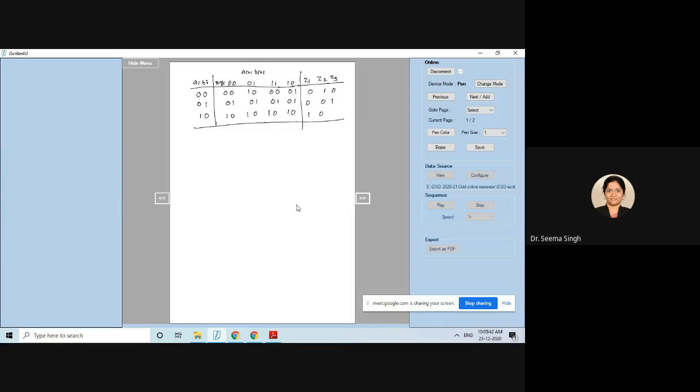Okay. Now, quickly we have to see our K-map. And I am writing AIBI as MSBs here. What are the inputs for this? Input is present state and present input, right? So present state is taken as MSB as AI and BI, and present input is taken as LSBs of XI and YI. Now very quickly you should see how to write this. So what you can see is 0, 0, 0, 1 and 1, 0. Of course it is coming here.